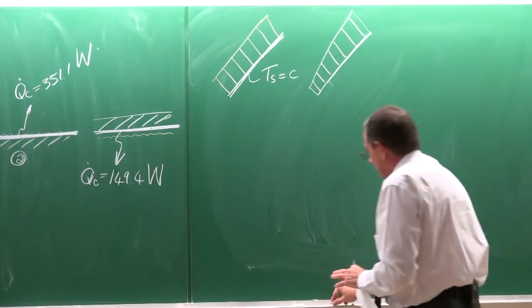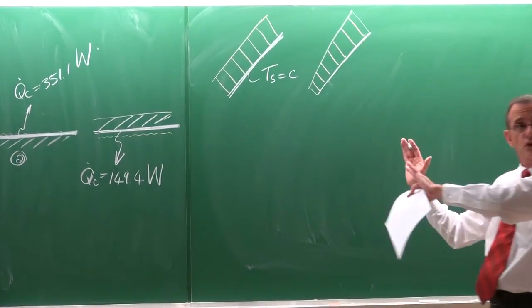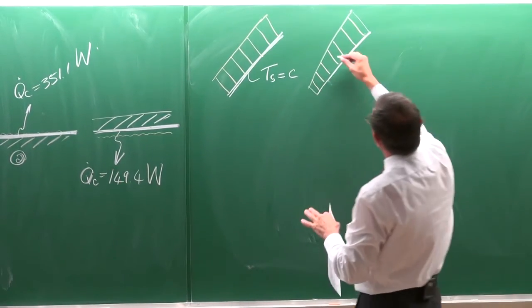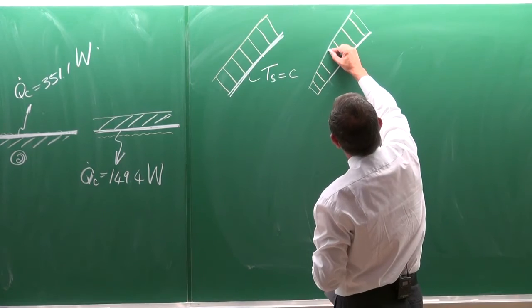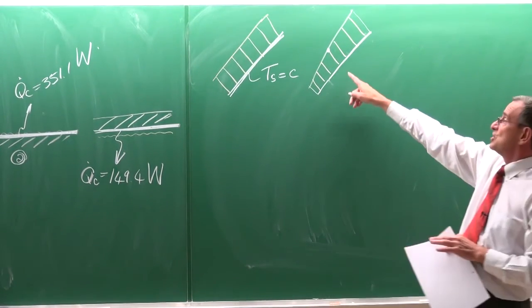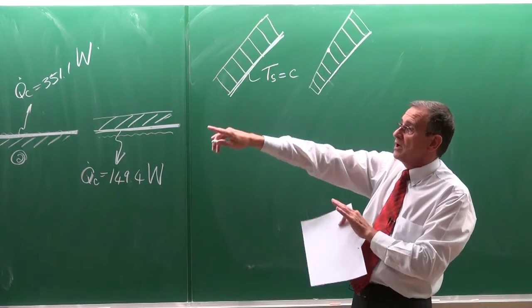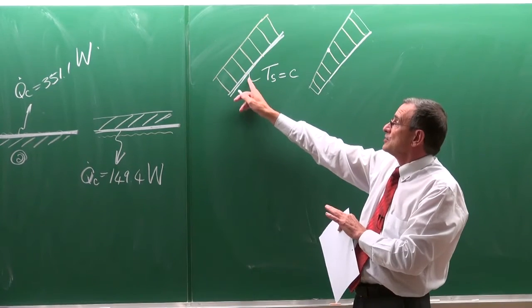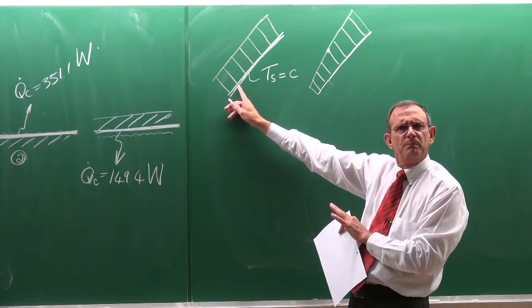Now, the fine print again will direct you in terms of the equations to be used. For example, with a constant heat flux case, you need to use that temperature Ts, which is the average temperature halfway through the plate. If you start with a problem like this, normally the surface temperature and the environment temperature are given, so you can calculate the film temperature.